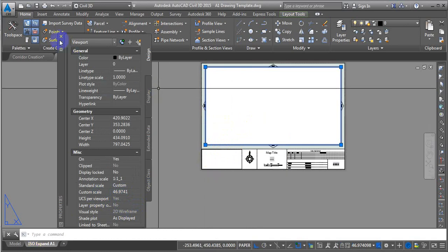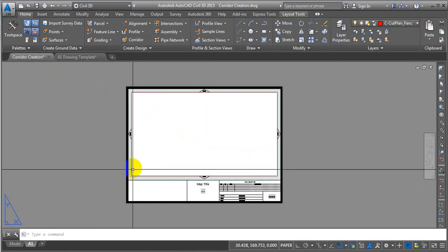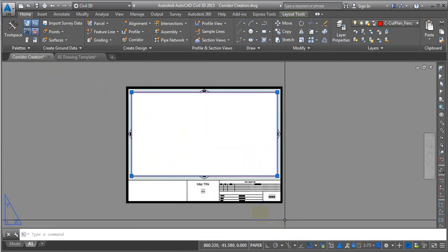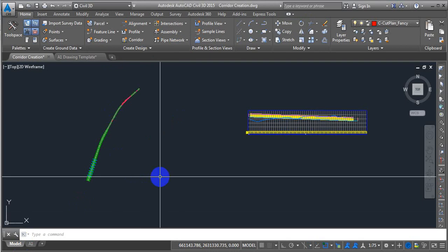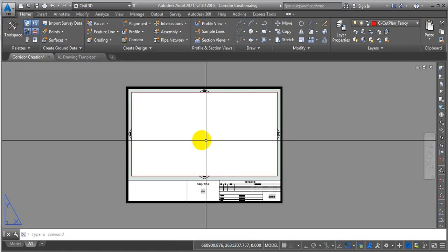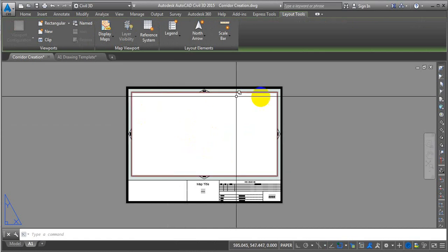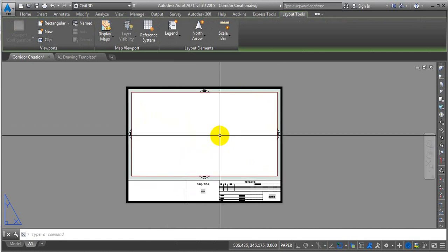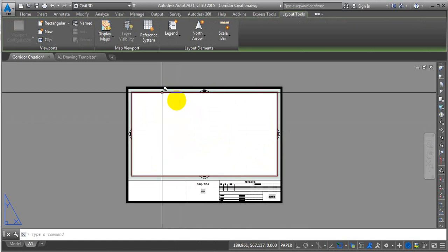I know that if I go back to my main model where I have my corridor and everything, my scale for automatic cross section should be 1:75, because in our previous video we made one section view, and then we adjusted that section view in this viewport, and then we said that we want 6 section views of that type arranged in this layout. And also at the end of the video we calculated a standard scale which was 1:75.